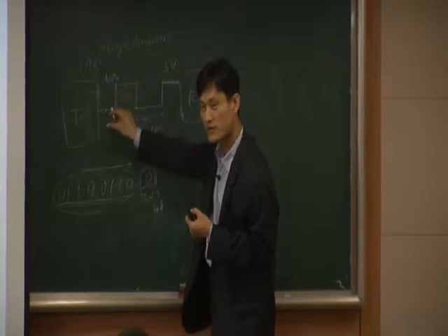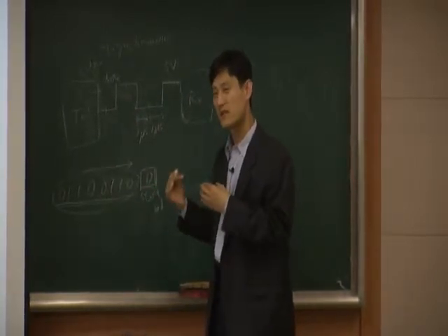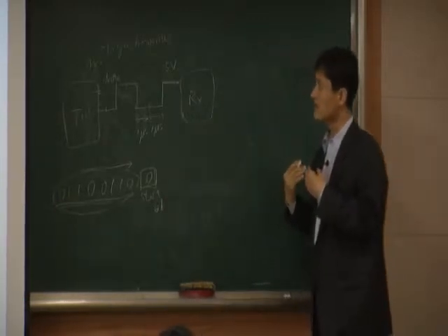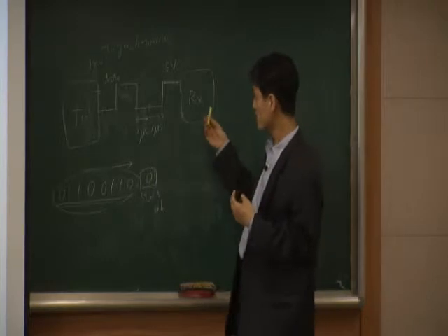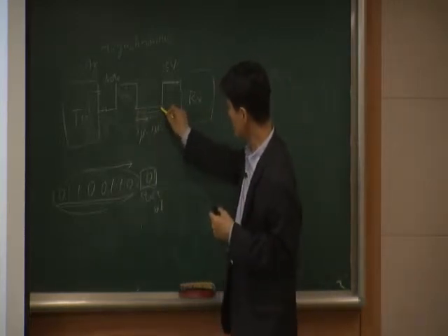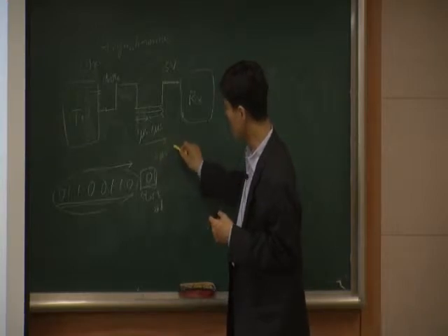Everything is 1 microsecond. That's what the transmitter was originally transmitting. But the receiver may think that, okay, this whole thing looks like a 2 microsecond start bit.